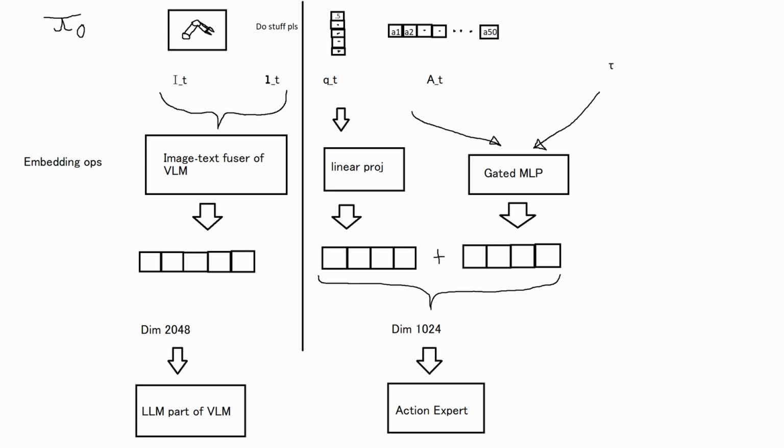And finally, number 4, they needed a chunk of robot actions. The research paper has this action chunk contain 50 actions. So from the current time step of wherever the robot is at, you would need 50 actions that it takes in the future from there to make a chunk. This action chunk drives what the model will be predicting. And I will get into the how and why of action chunk prediction as we get to the output of the model, but do know that it being a chunk of actions is actually pretty important.